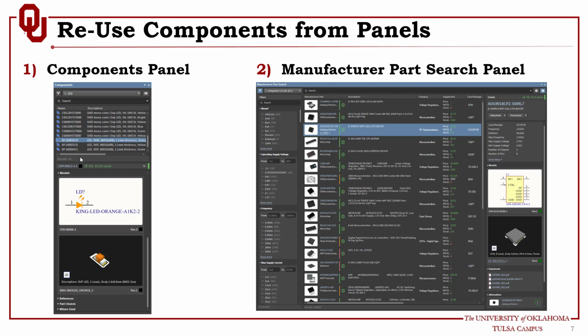These are usually either database libraries or integrated libraries. If you create a database library or an integrated library, this is where you can access and find a component in these local, file-based libraries.